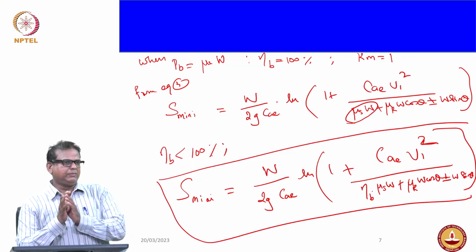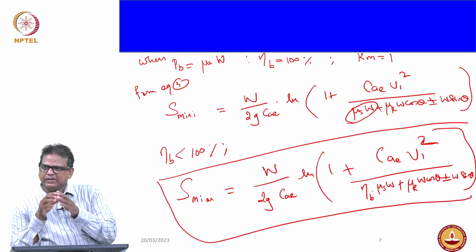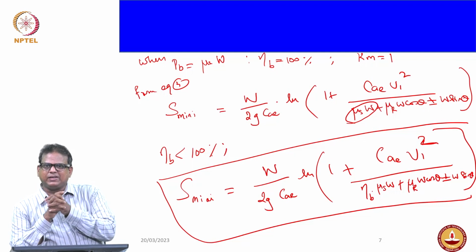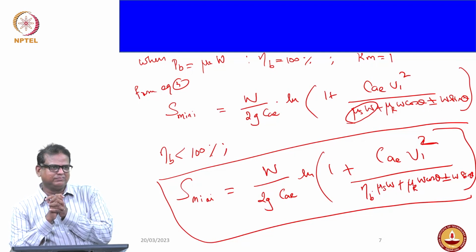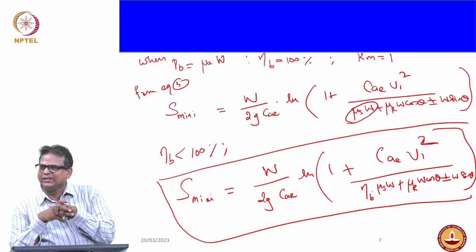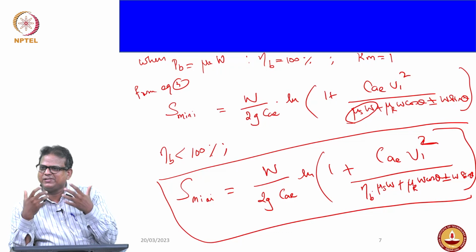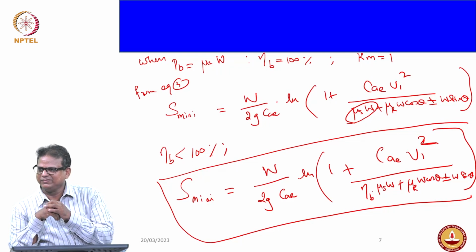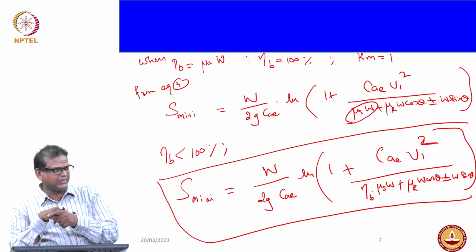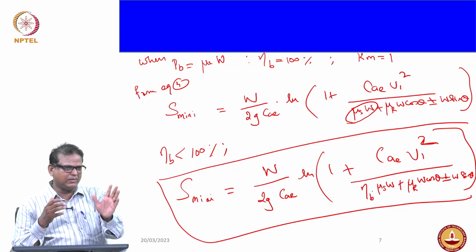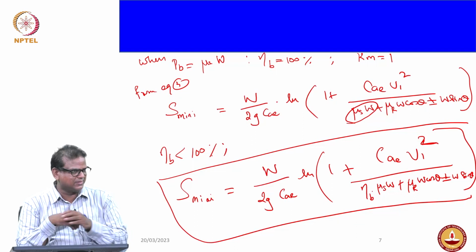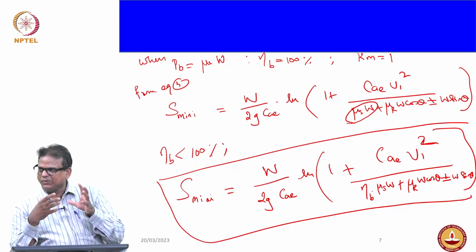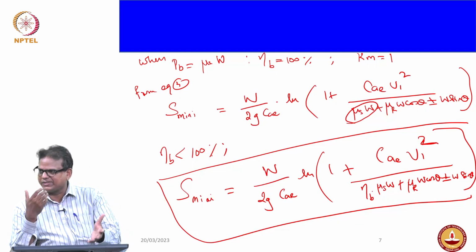Fine. Let me ask a question. This is in actual condition. In reality, what happens? What do you expect? Should we not consider the reaction time of the driver? The reaction time of the driver also should be considered, because by that time you will have covered a certain distance. That is also there. So some distance is already covered in the reaction time.